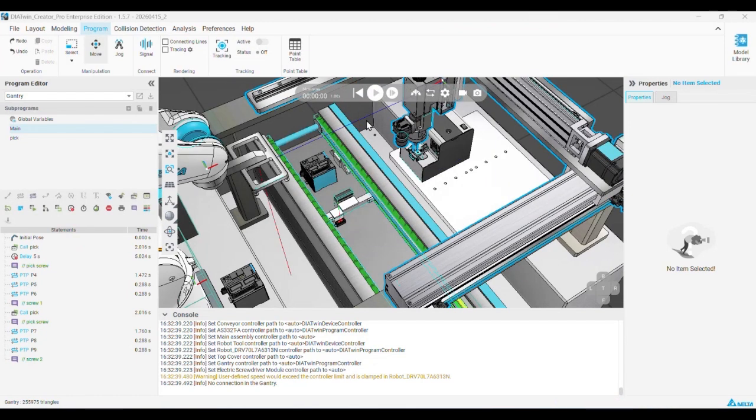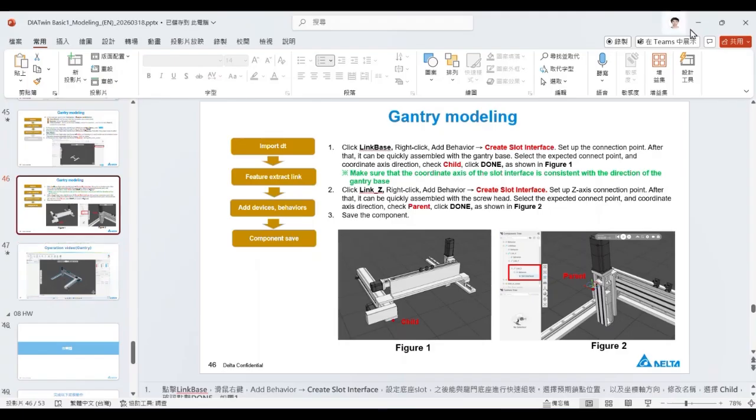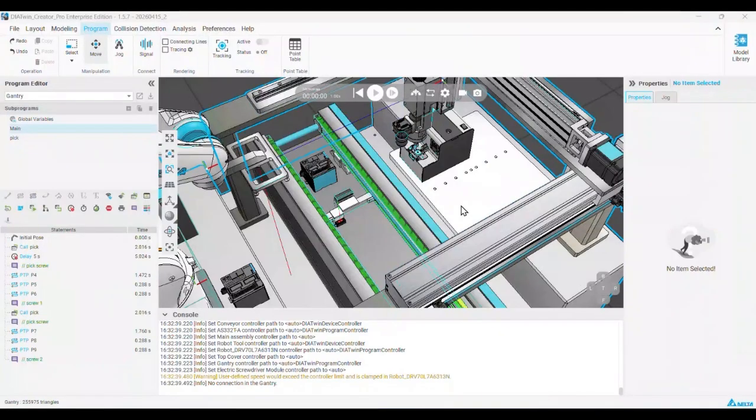So let's try this, and this will be today's process. Let's see if you are able to build this kind of gantry and process yourself. Also, like yesterday's training, we already have a master controller to handle it. So maybe you can use the gantry as a master controller to handle the robot and the conveyor, or you can just add another master controller. So there will be one master and 3 sub controllers to make a handshaking. It doesn't matter, just define it by how you want to design the process.